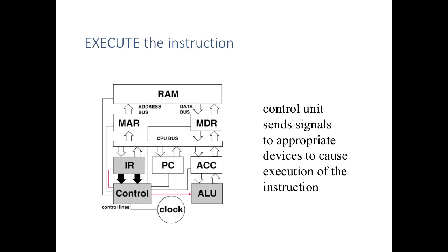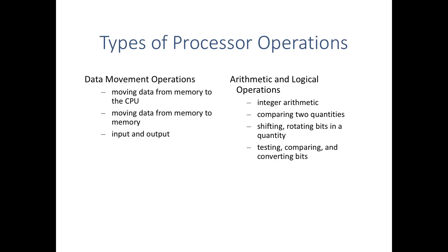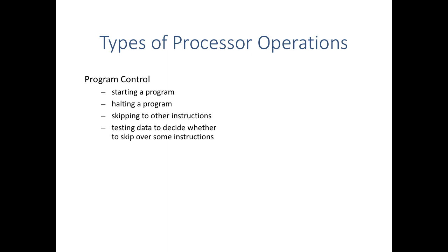That goes into the instruction register, and then the instruction register has to do an execution and a decode, and we expect that there would be some result written back to memory. And the program counter has to be able to respond to that instruction. So if it says, jump to another address, the program counter gets loaded, and then the program begins executing at the new address.